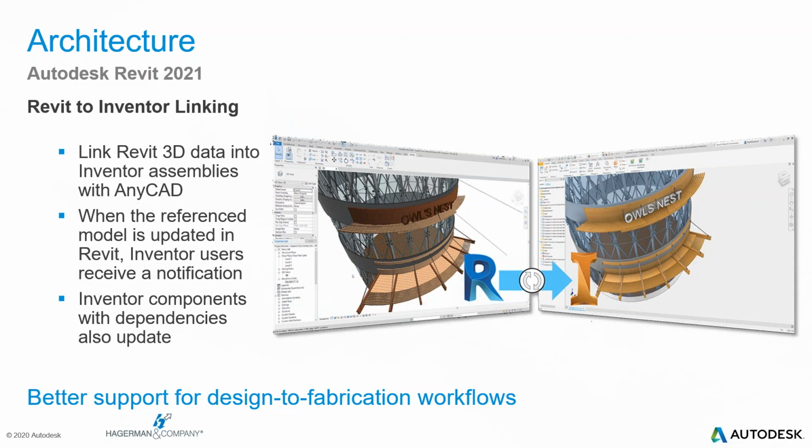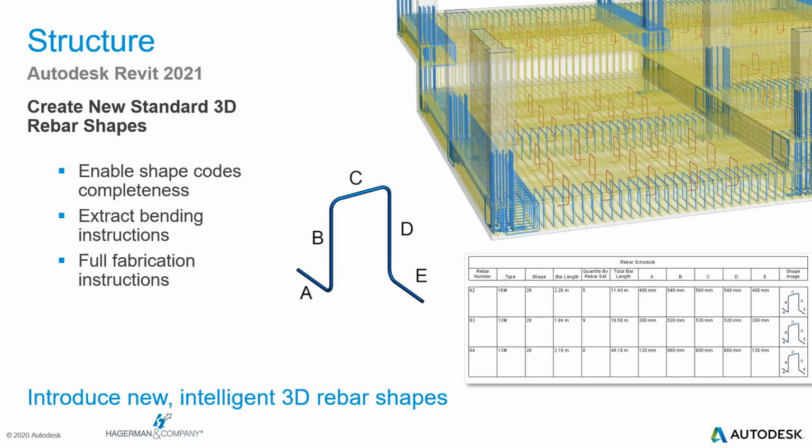This is accomplished by selecting the override hook lengths option in the properties palette and inputting the new length in the respective rebar shape parameter field. This is applicable for any rebar with hooks and requires that the hook lengths be assigned to a rebar shape parameter.